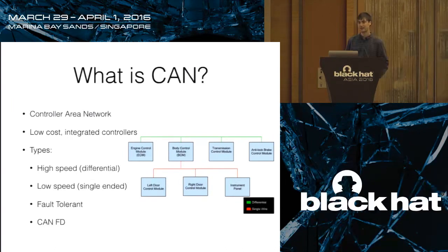And in a lot of systems now you see gateways. This is sort of a naive, really simple, fits on a slide diagram. Real automotive architectures are quite a bit more detailed and complex, and are also typically proprietary, so I can't put them on a slide. But this has a BCM, or a body control module, acting as a gateway between two buses. So it will let you get messages or get data from one bus onto another.